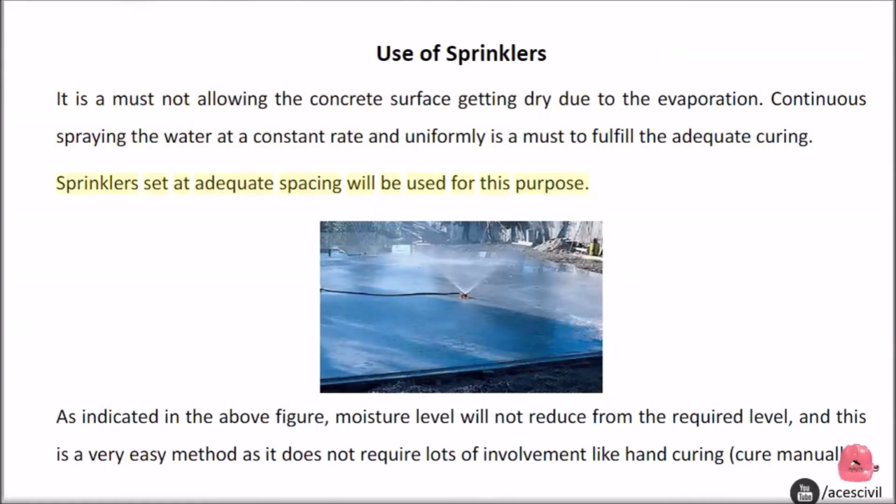Sprinklers set at adequate spacing will be used for this purpose. As indicated in the above figure, the moisture level will not reduce from the required level, and this is a very easy method as it does not require lots of involvement like hand curing.